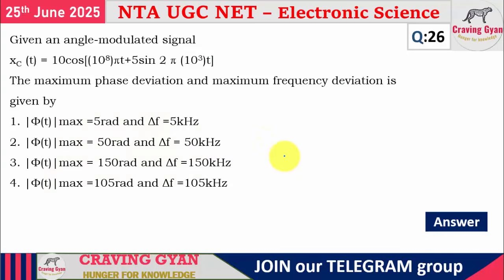In the 26th question, they have given xc of t equals 10 cos of (10 power 8 t) plus 5 sine of (2 pi into 10 power 3 t). They are asking what is the maximum phase deviation, that is beta, and what is the maximum frequency deviation, that is delta f. This equation, sometimes they will be calling it S of t.